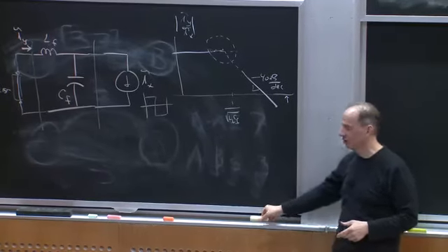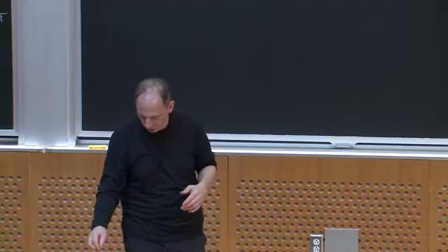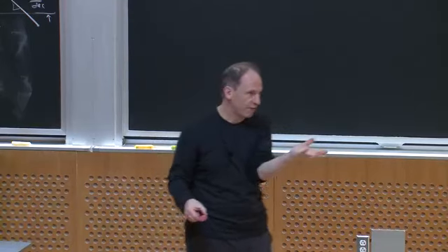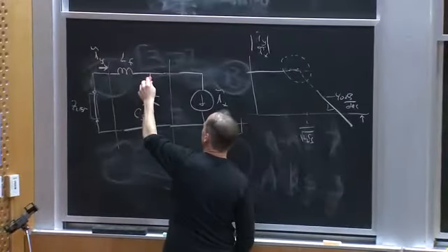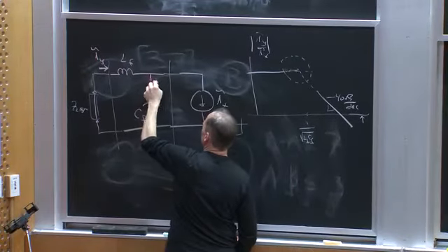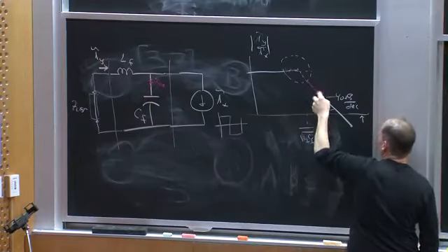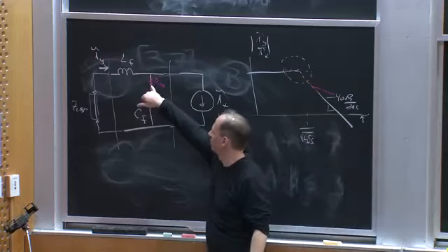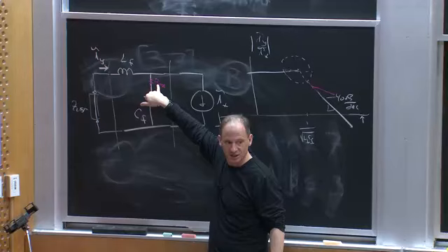But we have to be a little bit careful, because when we lay these filters out, first of all, there are internal parasitics, right? If I buy a filter capacitor, it's not perfect, so maybe it has some internal ESR, RESR, and what that would do is, instead of falling off like this, it would start to fall off at minus 20 dB per decade, because above some frequency this shunt path just looks like a resistance.